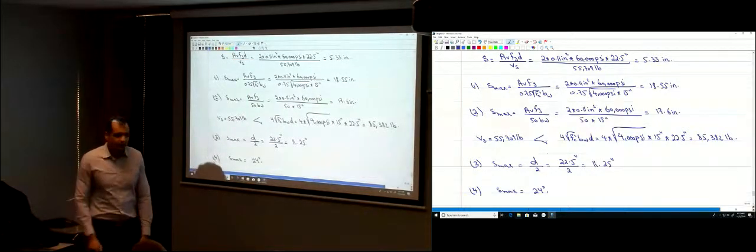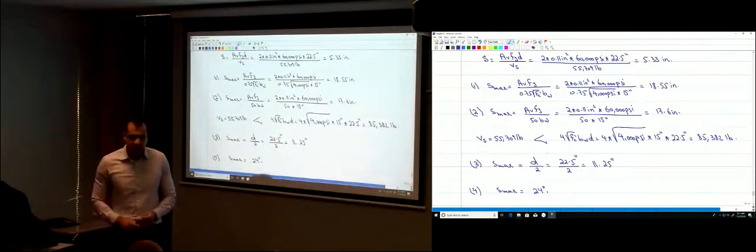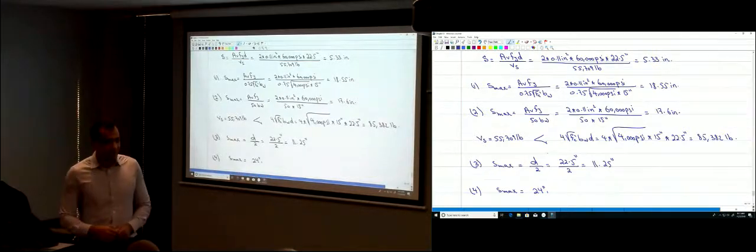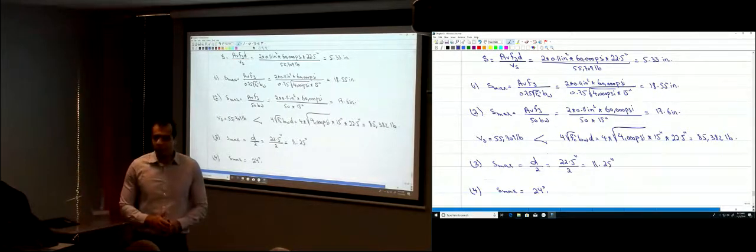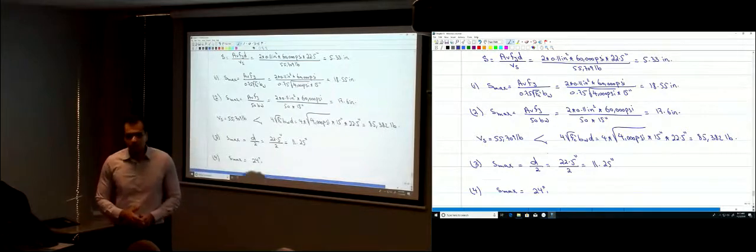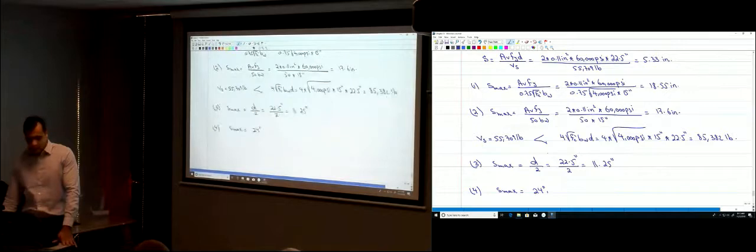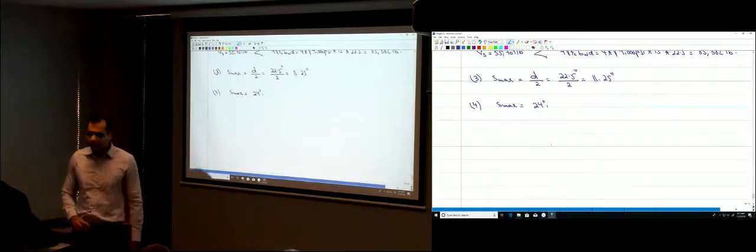What do you think about telling the site engineer the spacing between the stirrups is 5.33 inches? Why don't you just round it up to an inch? Those people, you imagine, are not going to measure 0.33 inches, okay?